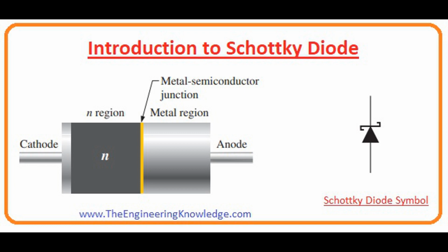When the voltage across the clamped component reaches the clamping voltage threshold, the clamping device activates and conducts, effectively limiting the voltage to the predetermined value. This prevents any further increase in voltage beyond the clamping level, protecting downstream components from potential damage due to overvoltage conditions. Voltage clamping is commonly used in various applications, including transient voltage suppression, TVS diodes.